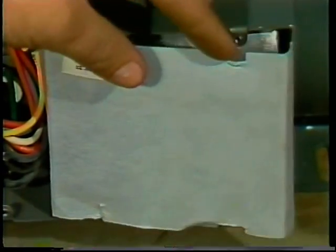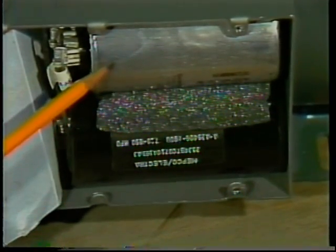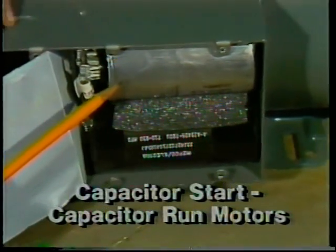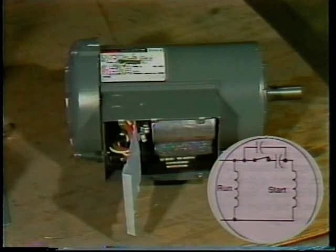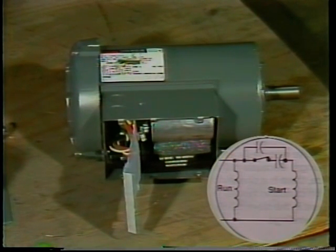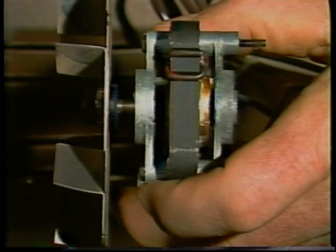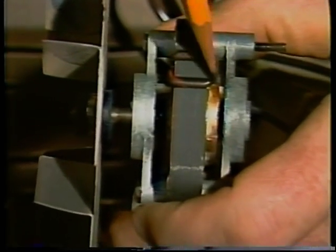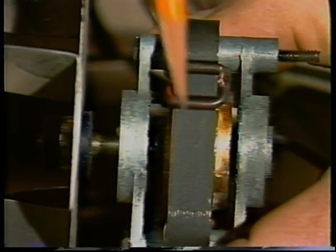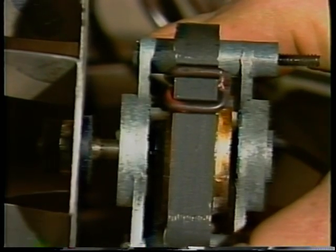Still other single-phase motors use both an electrolytic and an oil-filled capacitor. These heavy-duty motors are usually called cap-start, cap-run motors. The capacitors are connected in parallel while the motor is starting up. A centrifugal switch cuts out the electrolytic start capacitor during run. Small light-duty AC motors use a shading coil to provide startup torque. A shading coil is simply a shorted turn or two of heavy wire around a part of the stator core. Startup torque and efficiency are both quite low.